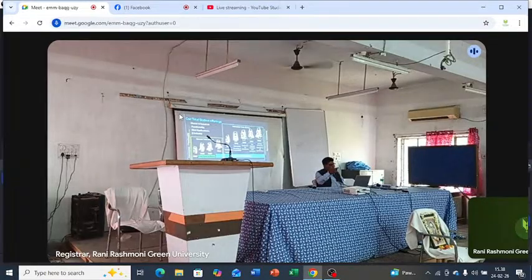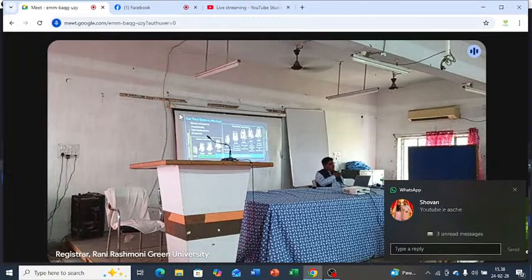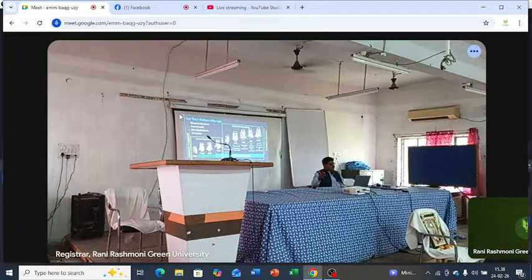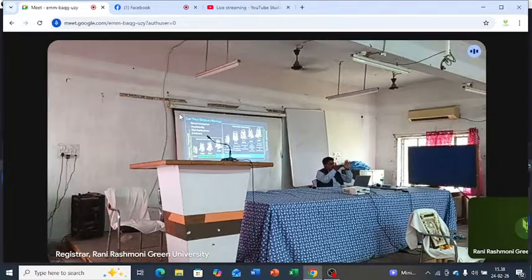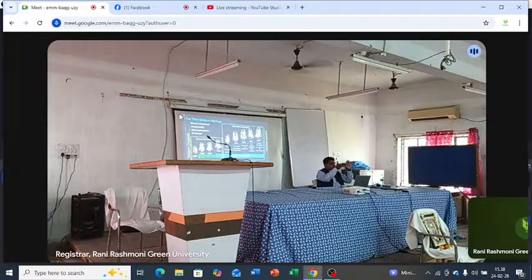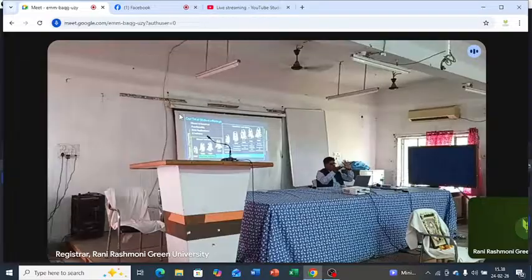After one hour, it again measures all the prisms around the targets, then compares with the previous values. If there is a deformation, or a difference between the measured values beyond a certain limit, it triggers an alarm. Say a dam wall: when the water is rising, it is supposed to move. But if the movement is very high, then there will be a catastrophic problem.